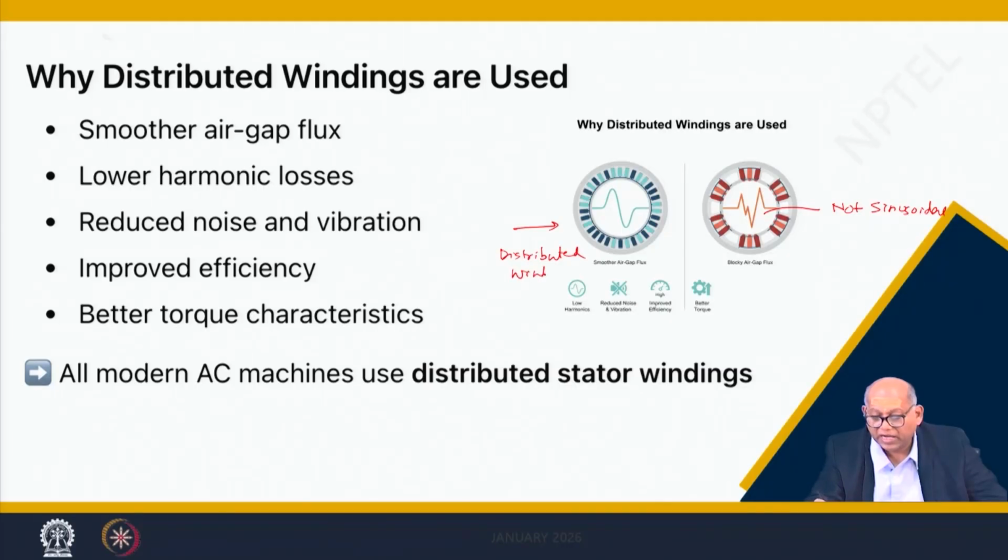This distribution has certain tricks, which are beyond the scope of this work. That means you should have a proper spread, in how the winding is distributed. These are all winding techniques, called armature winding techniques. There are different kinds of armature windings. These armature windings are responsible for making the flux wave or MMF smooth, not stepped. This is the whole idea of smooth.